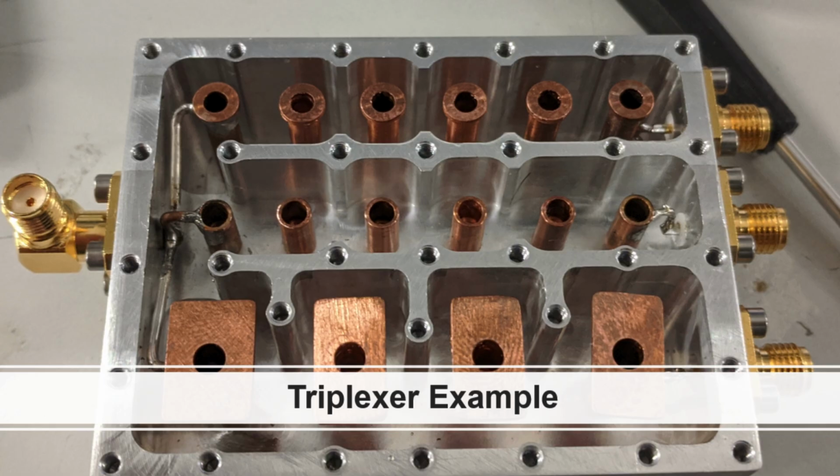Each one of these filters is a bandpass filter. The lowest frequency band is the one at the bottom of the screen, and you can see that because the rods are all about the same height, so you would expect each of these filters to be about the same frequency, except the rods at the bottom have a lot more capacitance to the lid, and that lowers the frequency. The ones in the middle have not as much capacitance to the lid, and the ones on the top side have somewhere in between.